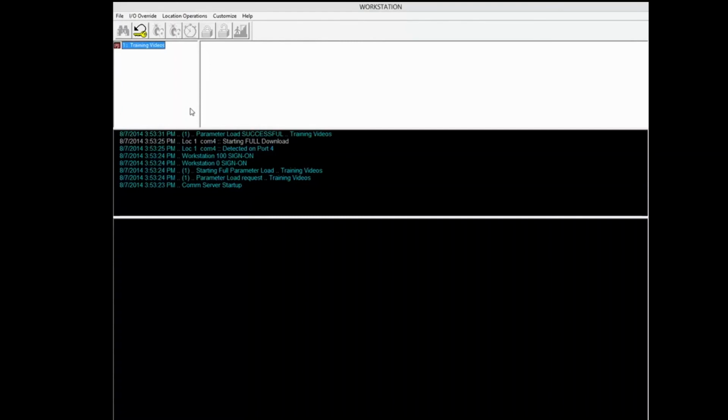These instructions are for testing connections to the 1040 series of DSX controllers using the RS-232 protocol. The 1020 series of controllers use the RS-485 protocol for communications. If trying to perform a loopback on a 485 connection, disconnect the RS-485 wires from the master controller and connect transmit positive to receive positive and transmit negative to receive negative. This will allow for loopback testing of the RS-485 output from the DSX USB or MCI modules.